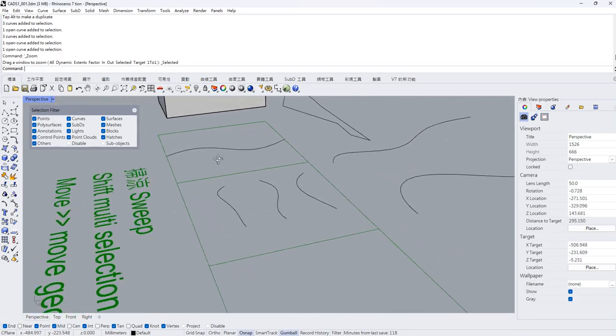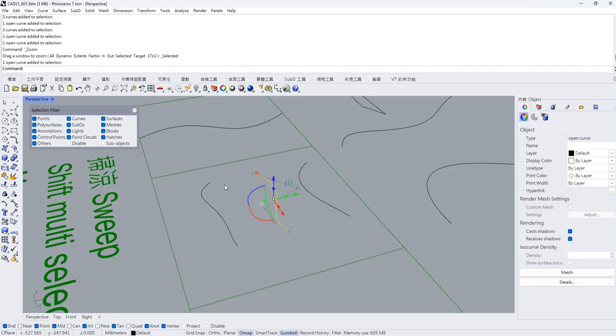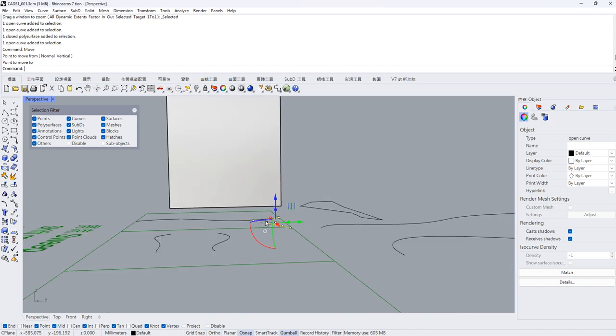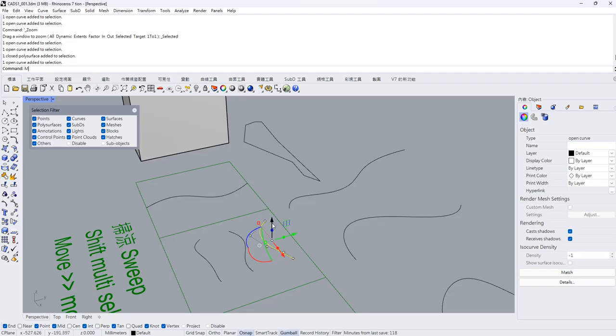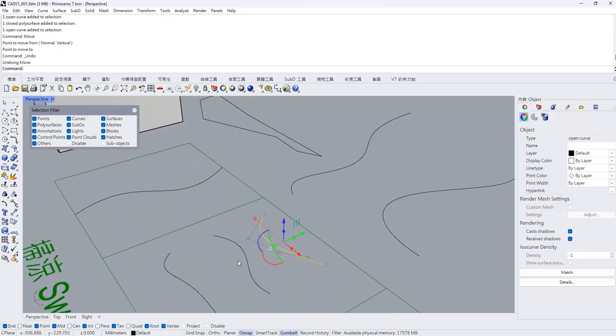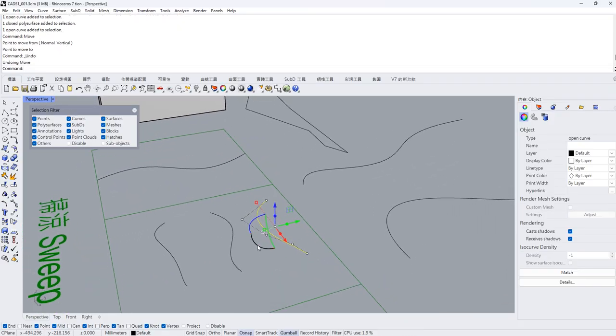The things we drew are actually flattened objects. They were snapped on the XY plane. So in order to make the curve a 3D curve just like this, we need to rotate it. Otherwise, if we just directly move this one to here, they are still planar and you will get a plane surface. So in order to make this 3D, the section has to be rotated 90 degrees, choosing the X direction.